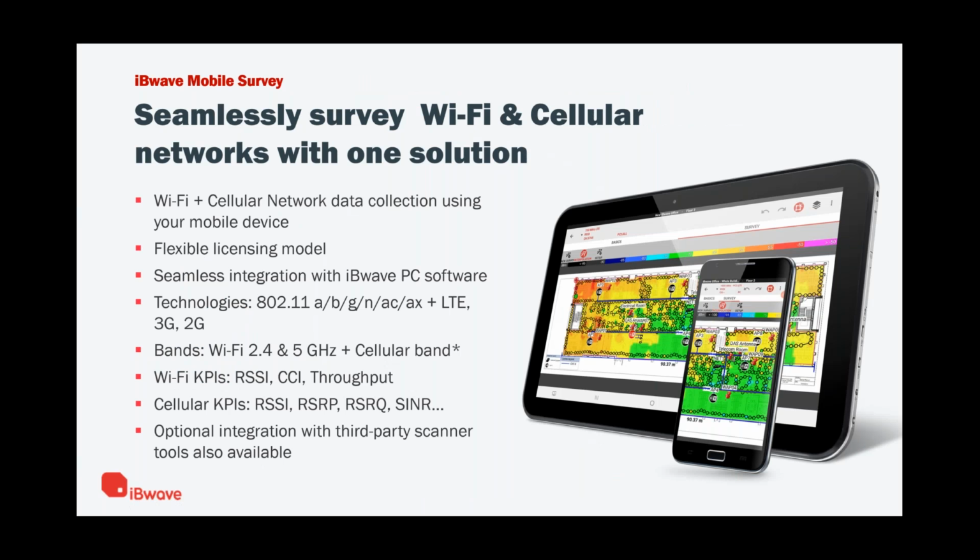Okay. So the iBwave mobile survey is an upgraded form of iBwave mobile notes. It's renamed to iBwave mobile survey and contains two different modules, which are the collection module and the interpolation module. The collection module enables the capability to do the data collection for Wi-Fi and cellular, whereas the interpolation module will convert the walk test data into an interpolated heat map.